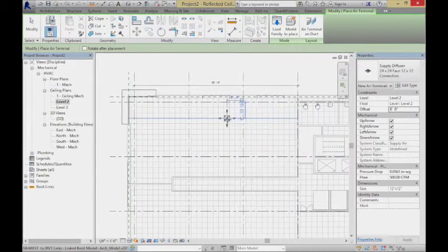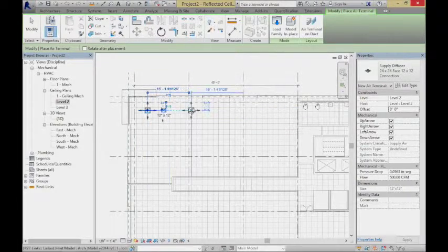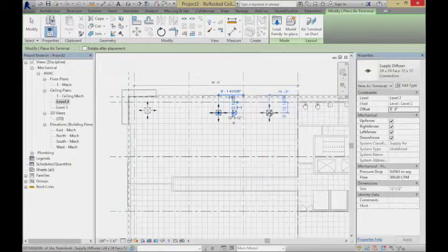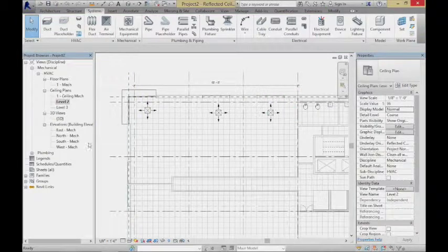So I'm going to put it at 8 feet. Here's what we're going to do. I'm going to start dropping some of these in. Whether I wanted 2 to 4 doesn't really matter; it depends on how many air changes I want. I'm going to put them out here towards the outside edge. So there's one. Maybe I'll put 3 in here. The reason I'm going to put 3 in here is that if I'm thinking about the structural system, I can see where the grid is. You're going to start thinking about where you want to put these relative to the grids, or where some of the beams are going to start showing up. You're thinking ahead a little bit to how these things are going to work together.